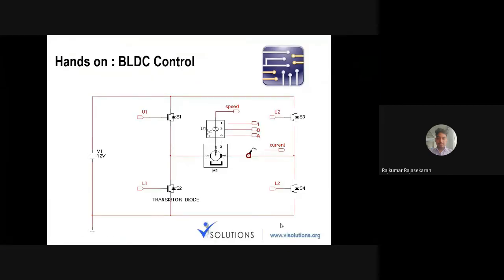In this case, you can possibly build a BLDC motor here, where you'll give the 12 volt input. You can find there is an H bridge, inverter control using the inverter option, and in the center you find the motor. After giving this input to the motor, you could see that you have a current measurement option.